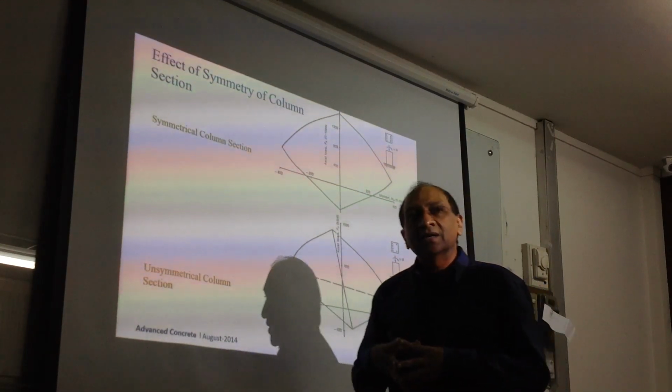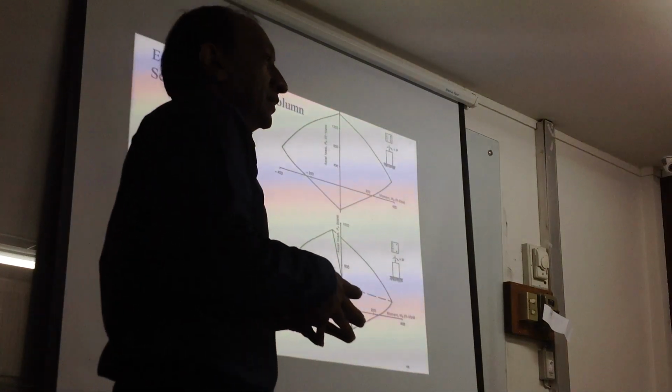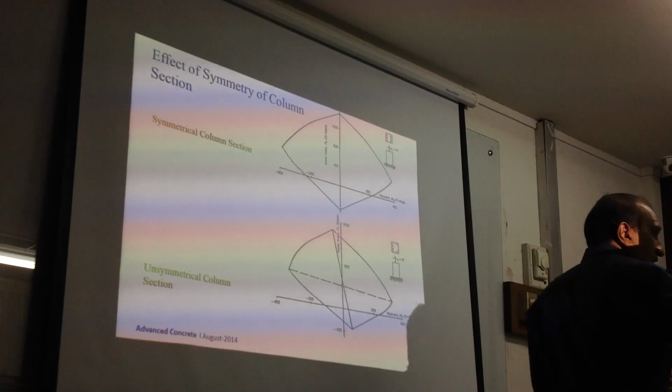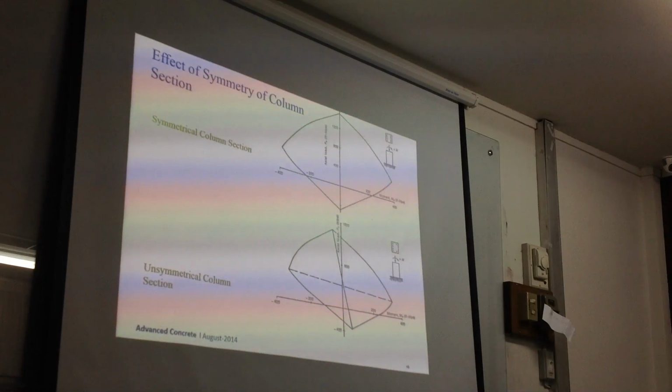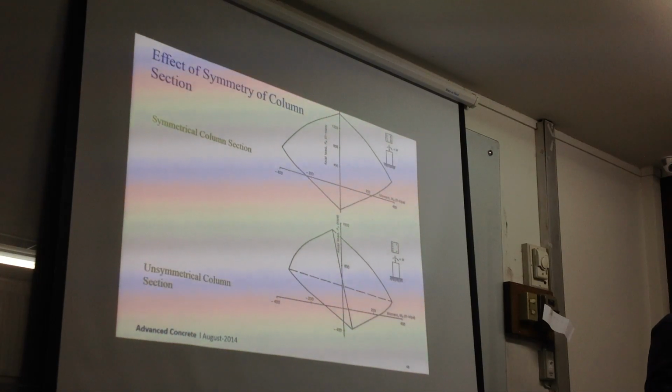So these things are important and they are often not recognized by the simple books and charts because they assume you have 16 bars, 12 bars, 8 bars in section, you don't have 11 bars, which is true. You shouldn't have 11 bars in a column normally. But sometimes we need to do that.